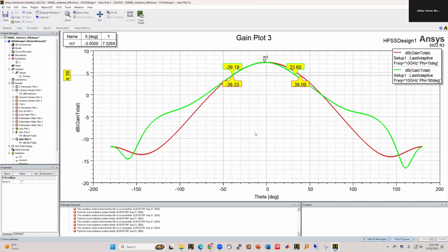Okay, so that's about the half power beam width. One thing I want to mention is you can actually use, let's say, the 80 degrees and the 75 degrees and the 4 pi over theta E theta H, which is the half power beamwidths in the two planes, and then take 10 log of that. I actually just did that. I calculated it, and it turned out to be around 8 dB or so.